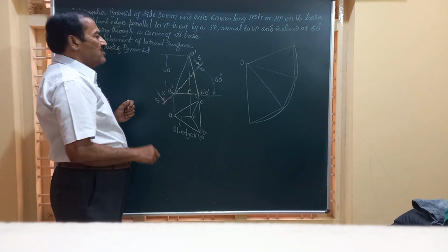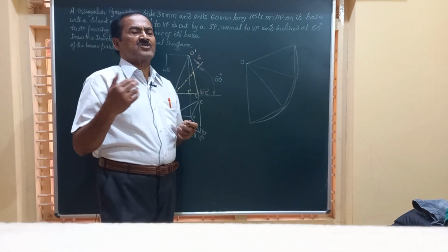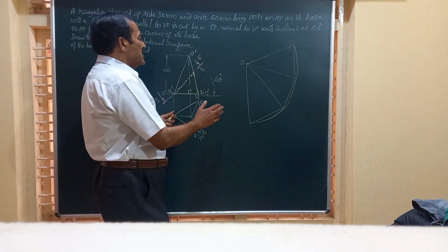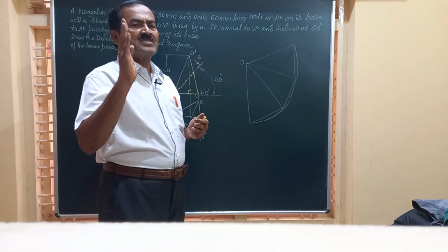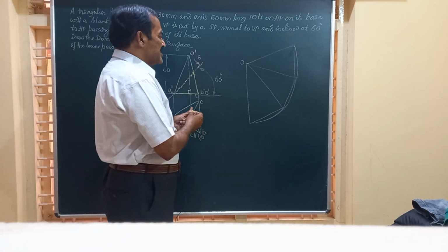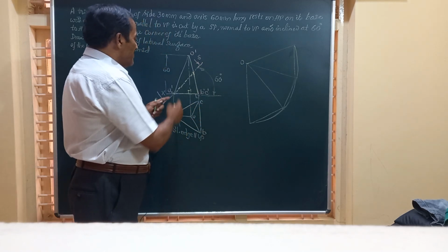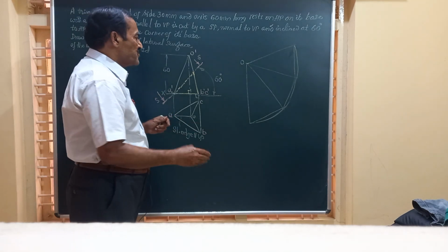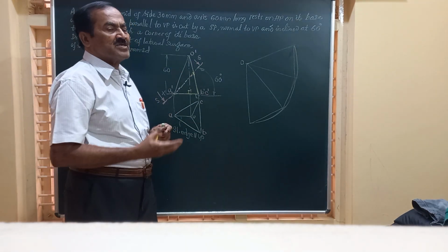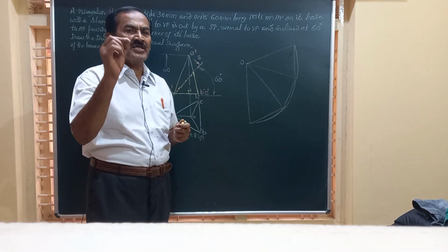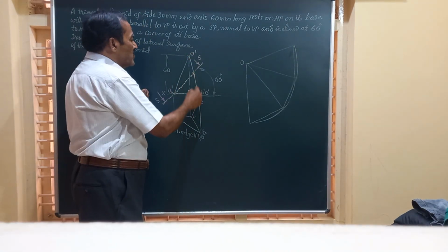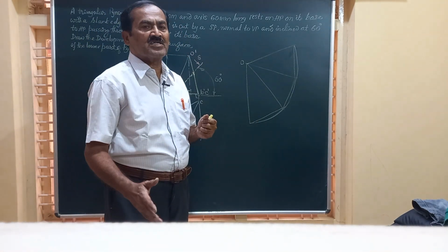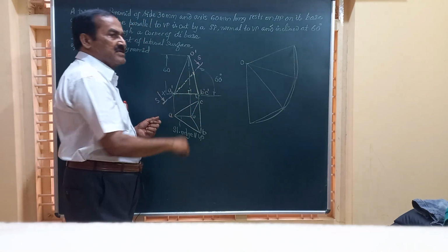So friends, now let us assume that the solid is not cut by any section plane and hence we are going to have on the lateral surface three isosceles triangles. Now here you can start from the edge O dash A dash because O dash A dash is totally removed from the section plane. And here you have to be very careful. By chance if you start from O dash B dash or O dash C dash, you are going to have the development in two pieces, which is not permitted for a single block.